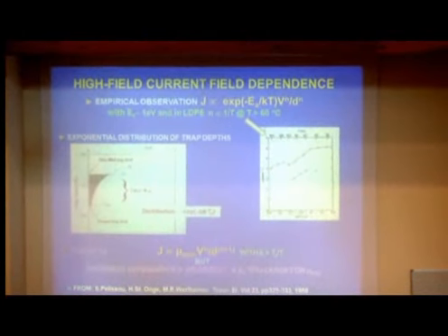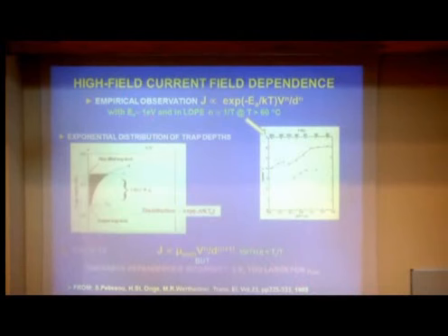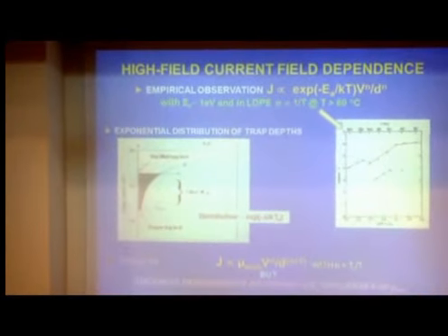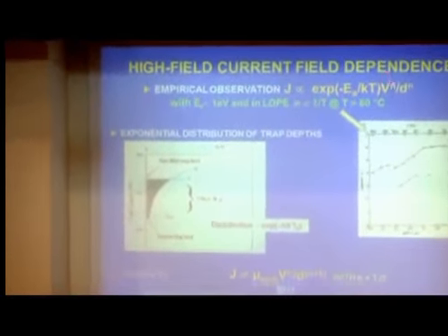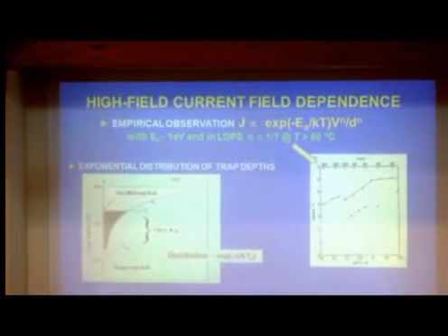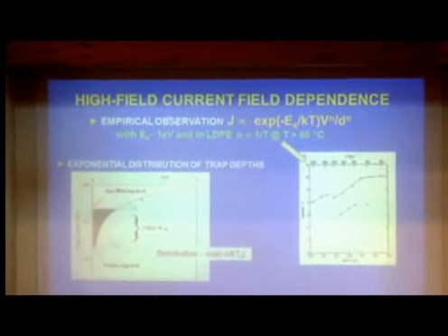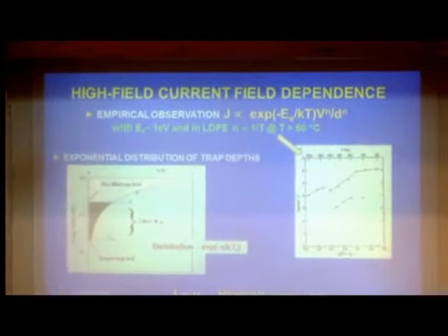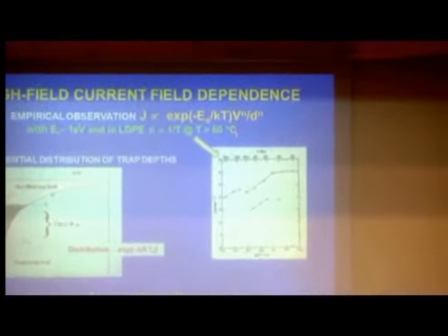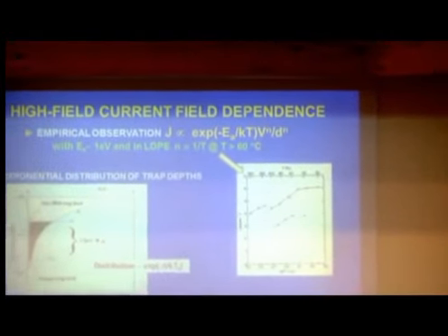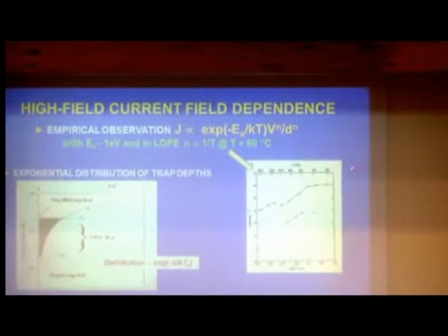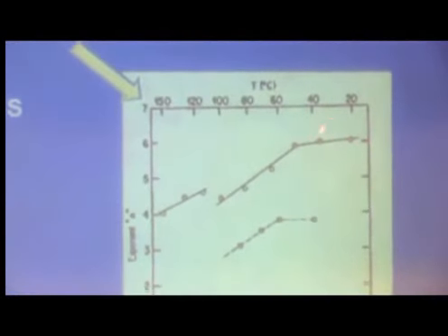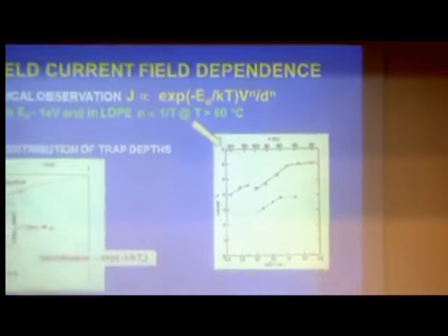So let's come to what we know, or at least what we knew in 1988. Analysis of quite a few different polymers showed that the current density dependence could be split into a thermal dependence like this, with an activation energy, usually quite high. I've put here 1 electron volt. In the cable data that I've just shown you, it was about 1.8 electron volts. And a power of the voltage. Actually, a power of the field. This term is quite important. The power over the range from room temperature to about 60 degrees centigrade is effectively constant, and then it goes as 1 over T, the temperature.